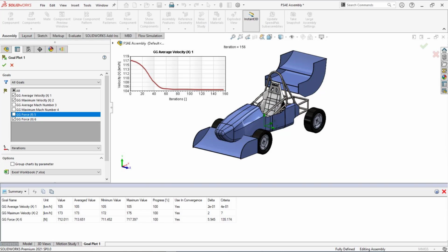one more very important thing is, to consider the drag and lift forces, we need to take the appropriate F of x and F of y values. Keep in mind, F of x, that is the force along x direction, will indicate the drag force. Force along y direction will indicate the lift force. So in previous sessions there might be some misunderstanding. To clarify that, you need to remember F of x, the force along x direction, will indicate drag, force along y direction will indicate the lift force. Okay, yeah.